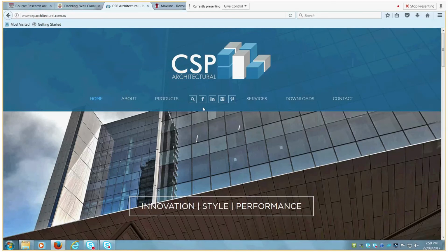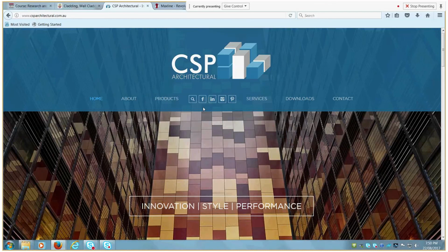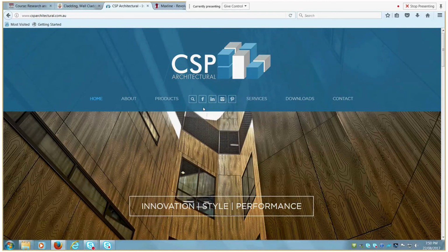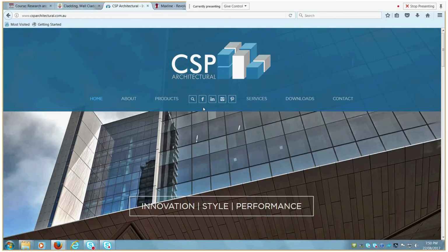Particular companies do have particular profiles they use. Something as simple as, the issue we had was the castellation, which was 86 by 32, and it had a particular three upstand mould out of it to give it a certain look. I tried to source it from a local supplier, but they had a slightly different profile, which wasn't good enough for this client. And we couldn't go to a wood machinist to create the profile because it had a copyright on it.